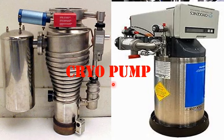Dear student, please note that it is not possible for a single pump like a turbomolecular pump, cryopump, or ion sublimation pump to create 10 raised to power minus 8 to 10 raised to power minus 10 torr of high vacuum. So these pumps in molecular beam epitaxy are basically used in combination. It depends on the system, but this high vacuum is produced by a combination of different types of pumps like cryo and turbomolecular. However, the cryopump is most common in molecular beam epitaxy.